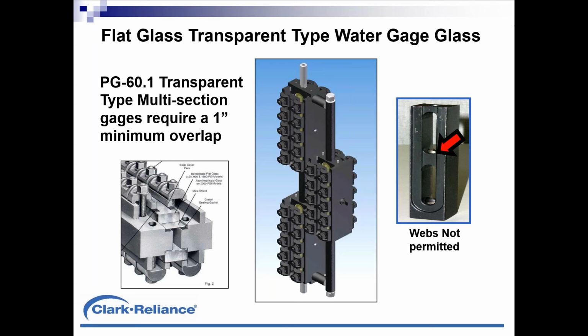Having said that, I'd like to bring to your attention the image shown on the right. Where that red arrow is, that's pointing to a structural web. Structural webs are used by process level gauge manufacturers, including ourselves. We have a Jurgensen brand of process level gauges that are used in countless applications for fluids other than steam and water. And that structural web, even though it has a hole through the center of it to pass the fluid, it can obstruct the operator's view of the level.